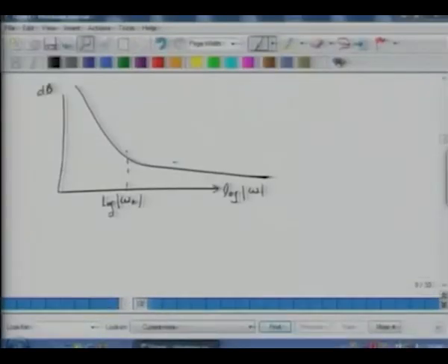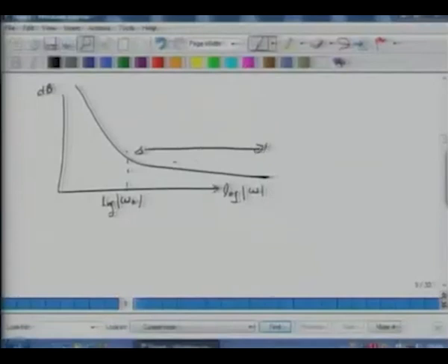And what that means is that if I place this microphone very close to the source, what will be the measurement? It will faithfully record high frequency data because the response curve is flat in this zone. But it will record low frequency information at a higher decibel level. Now when I play the same soundtrack, in reality, suppose I am speaking, my low frequency sound or information gets recorded at a higher decibel level, high frequency gets recorded at quote unquote normal level. When I play the same soundtrack again, I will sound like a person who has more bass.